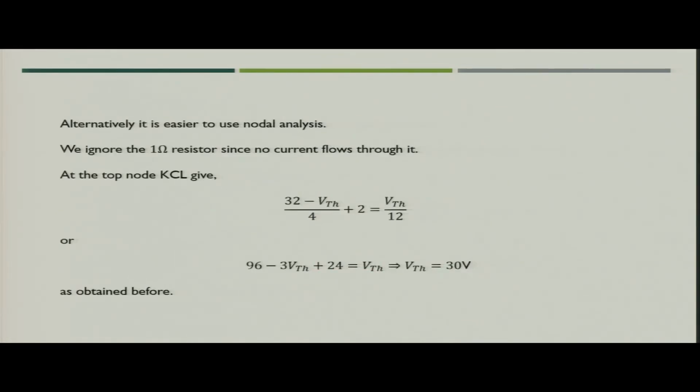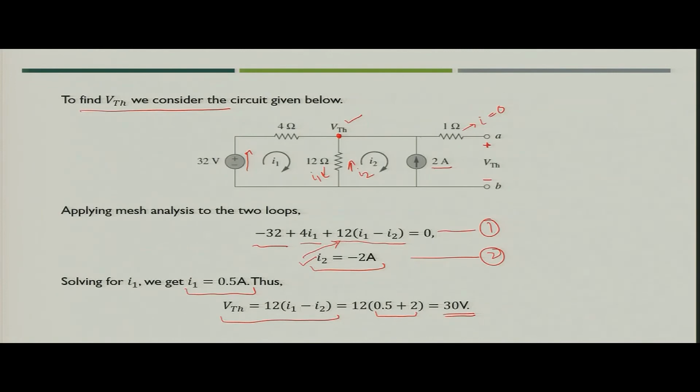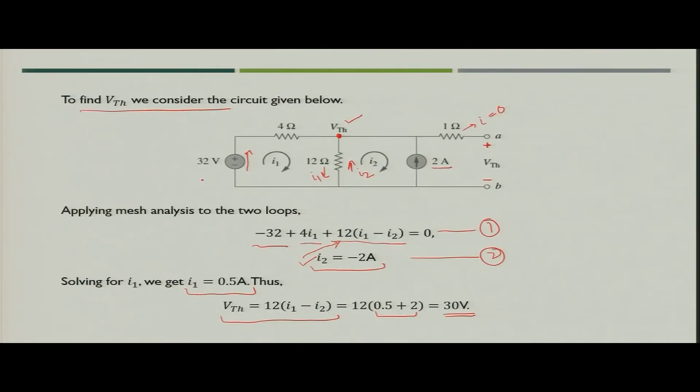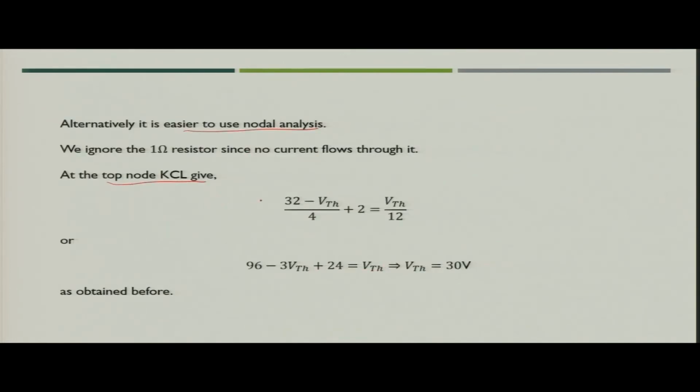Now, instead of mesh analysis, you can also apply nodal analysis. If you apply nodal analysis at this node, because this is the node where you are seeing the voltage VTH, that means you have to use Kirchhoff's current law here.